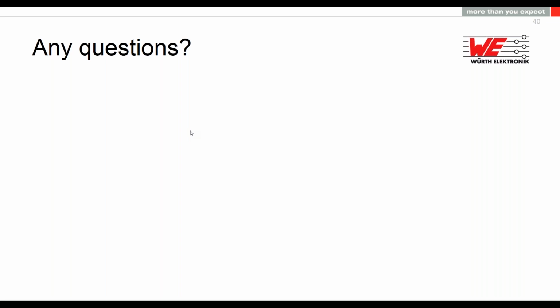So the first question is, when does a CMC saturate? Well, this is a really good question. A common mode choke saturates as well. It is something you will not find in a data sheet, because it's very difficult. It actually can be calculated and also measured, but it is not part of the data sheet, because when you drive the standard useful current or signal, you have a current compensation.